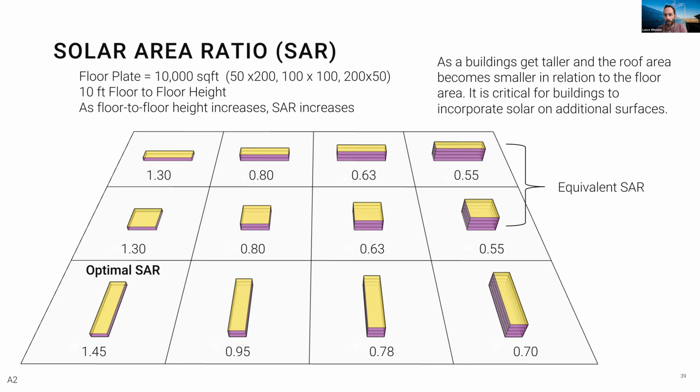I'll jump in here and just add that George Kelly did add a good comment. A good way to think about this right away is that if you put a dark absorbing PV on the side of your building, that PV is 22 to 23% efficient at best at this point. And so 23% of that absorbed energy is not going to be contributed towards heat load. That's going to be electricity. But within the visible wavelengths, if it's black, that's 50% of the sun's energy. So the rest of those infrared wavelengths could also be contributed towards heat gain.